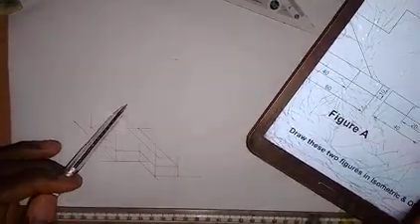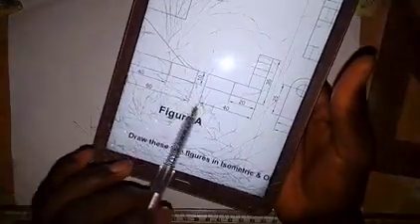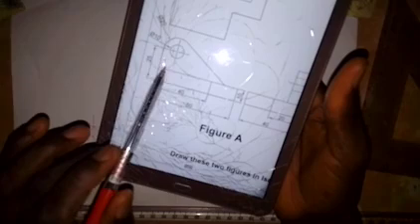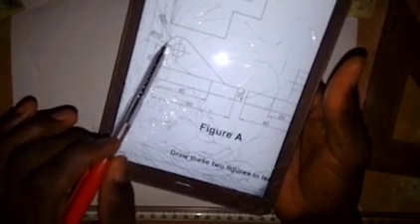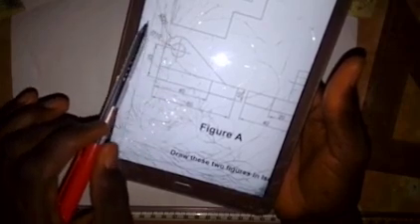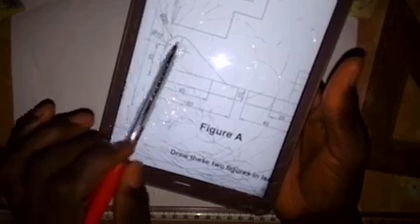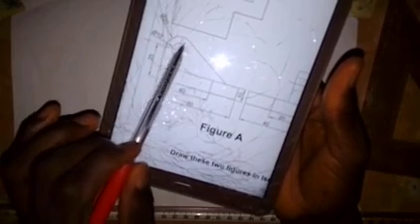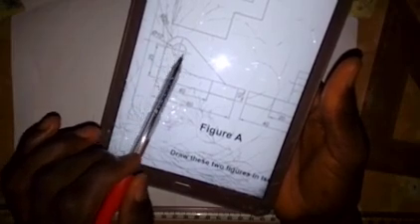So we have to draw a vertical line 25 millimeters up. Then coming to the front elevation, the diameter of this arc is 20. That means we have to construct a square of length 20 millimeters for us to get this curve drawn, and the diameter of this circle is 10. So we have to take note of that.